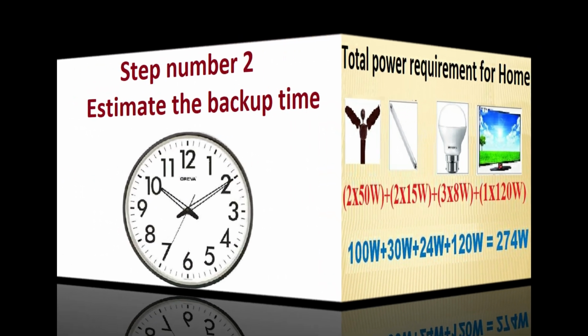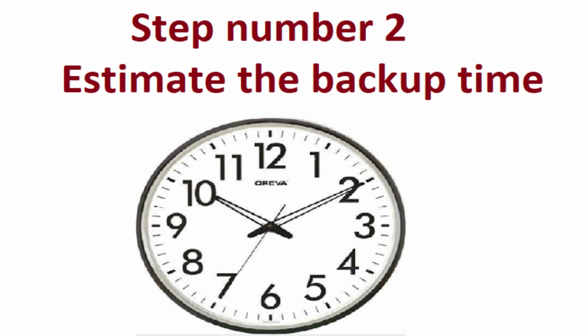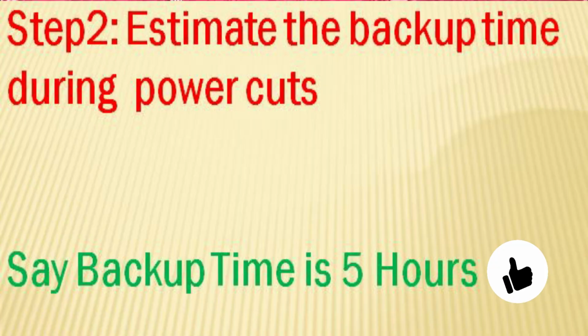Step number 2. Estimate the backup time during power cuts. The next biggest question is how much backup time you want. Actually, it depends on you, maybe 3 hours, 4 hours, 5 hours, etc. Say you want the estimated backup time to be 5 hours. Let us assume. Now please keep in mind the power requirement is 274 watts and backup time is 5 hours. Now go to step number 3.